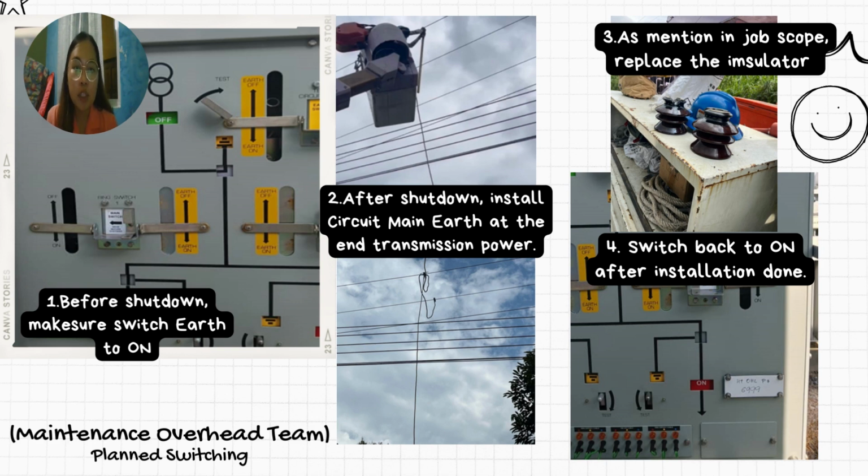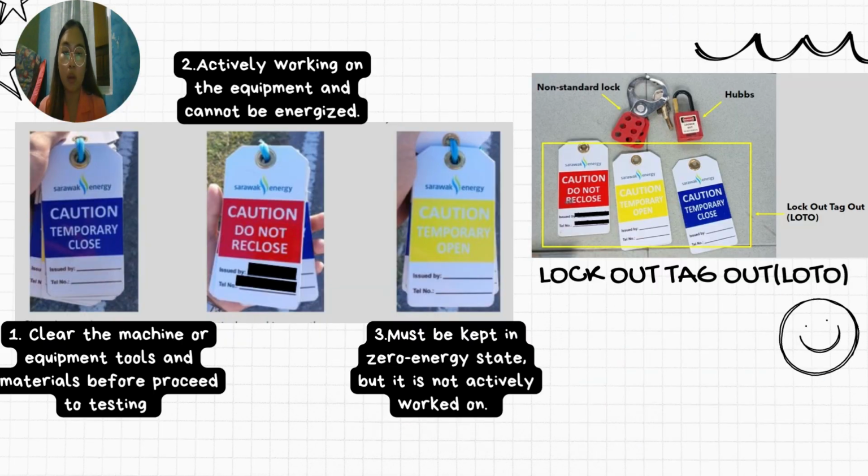Then, as mentioned in the job scope, replace the insulator. And then switch back to on after installations are done. And also, after applying circuit man earth, make sure to detect it with a voltage detector first and then apply the CME.